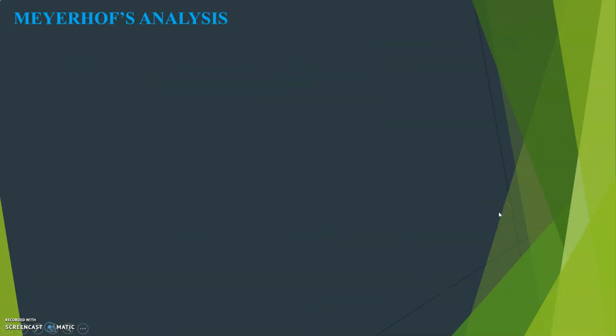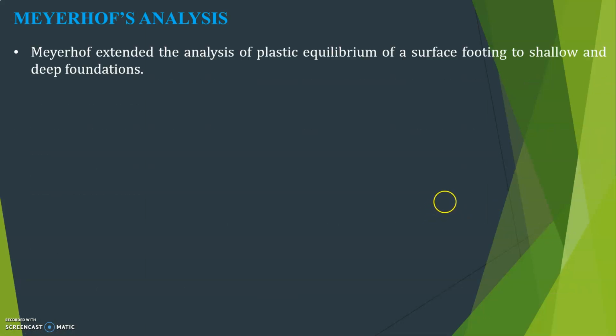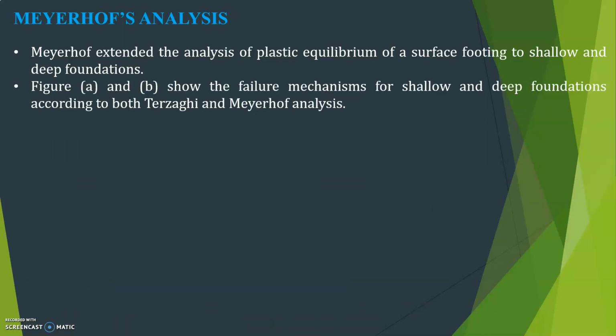Okay, next let us go for Meyerhof's analysis. Till now what I have discussed is Terzaghi's analysis. Let us see what is Meyerhof's analysis. Meyerhof extended the analysis of plastic equilibrium of a surface footing to shallow and deep foundations. Terzaghi's theory was only for the shallow foundation, but Meyerhof extended the analysis to deep foundations also.